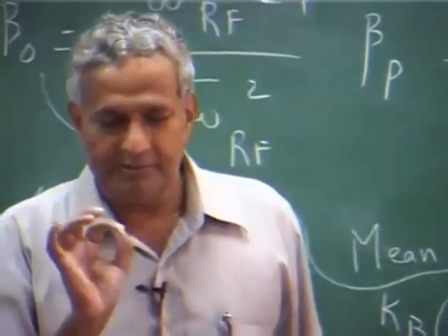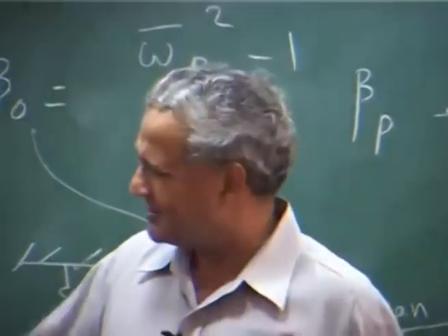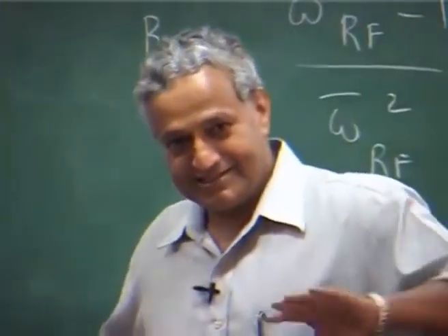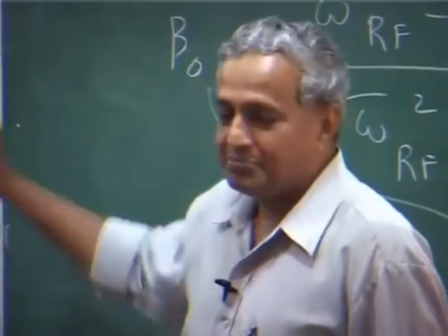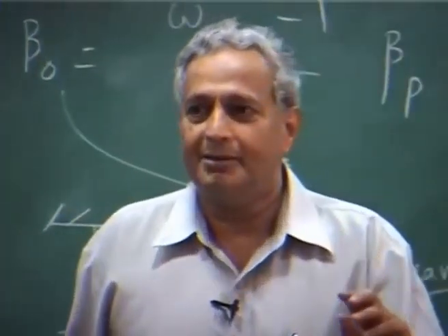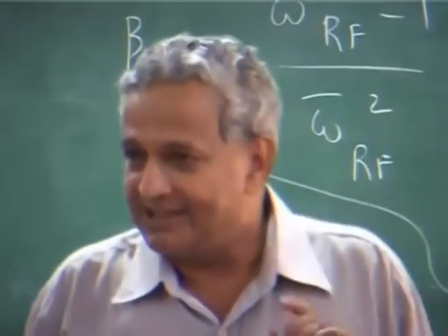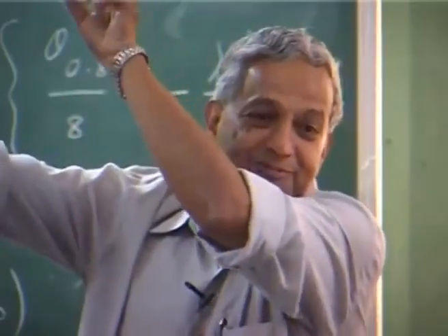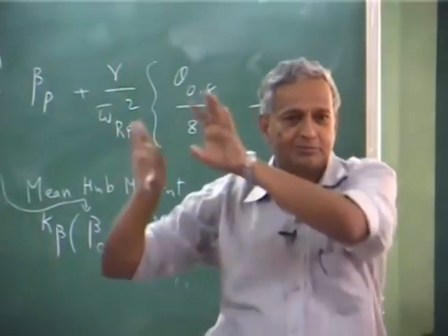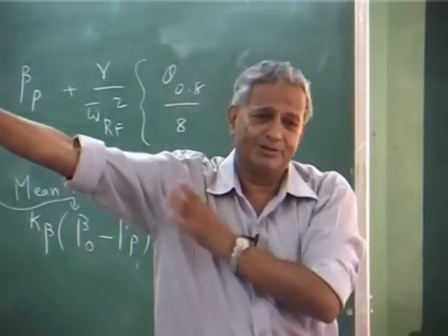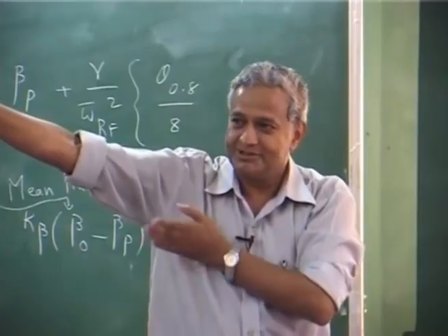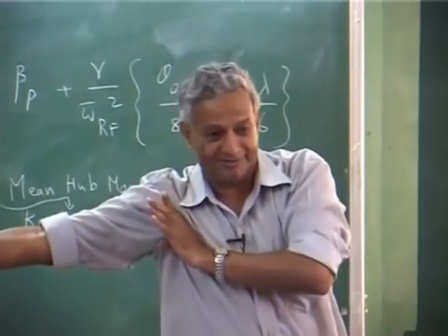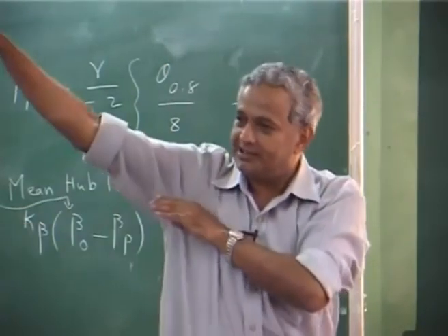is easier. That is why all are very important, but it has an effect on damping also, that part we will come to later in the stability and other aspects. Right now the precone is given to relieve hub mean moment slightly, otherwise you have to design a bigger hub. Because the centrifugal force will try to bring it down, the aerodynamic force will try to take it up. If these two moments are equal, it is kept at the same location, that is all. Okay. But if it is fully up, it will try to bring it down. If it is like this, it will take it up.